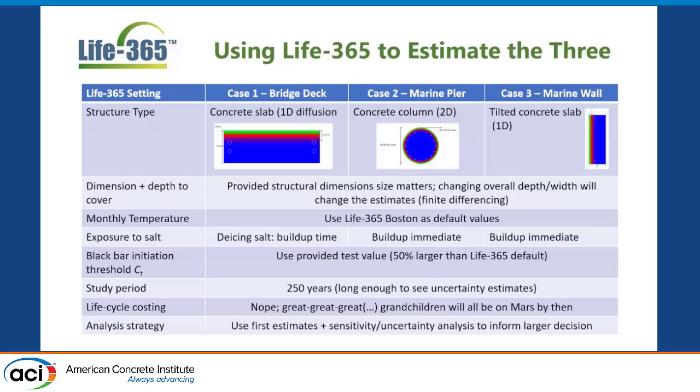That makes sense for a bridge deck, maybe in the wintertime where cars are coming in and bringing road salts to it, that kind of thing. But it doesn't make sense for a seawall. You're going to be getting maximum concentration right away, every day. As soon as that thing's up, you're going to be getting maximum. So the time to get to maximum is different across these types. That's where I'm saying buildup is immediate, whereas the de-icing salt buildup is over time.